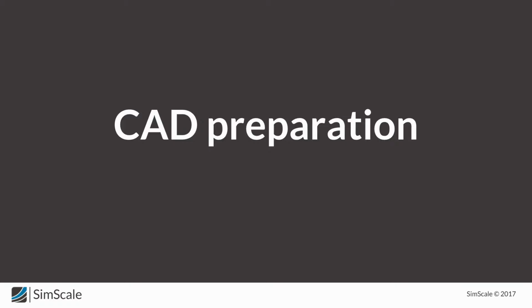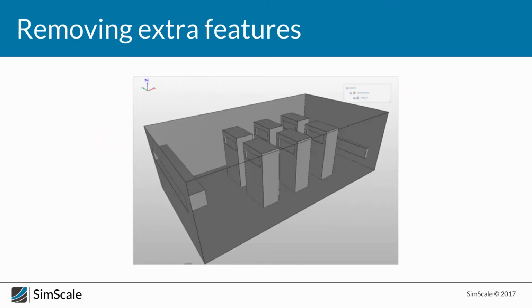We are trying, with simulations, to make a model of the general room itself. And the first step that we should take is to remove the unnecessary features that are present within the domain. All the door handles, or the cables, or the little knobs and chamfers, the things that will not have a significant influence on the overall performance of the room need to be taken apart.